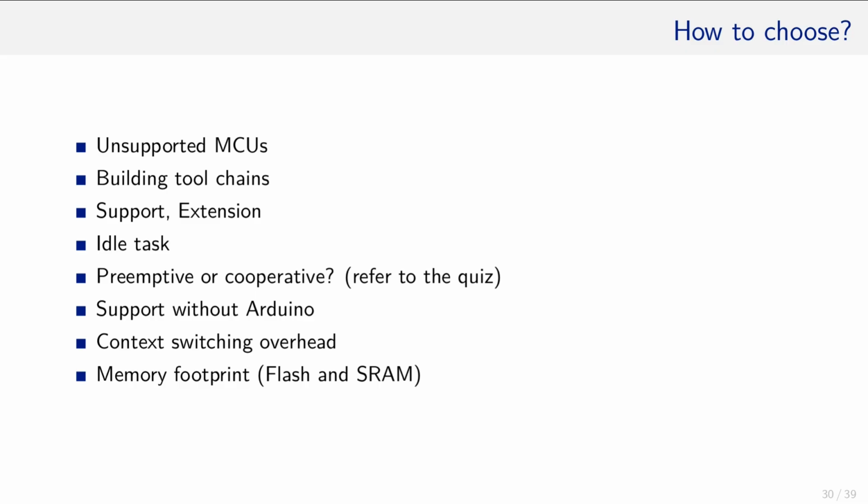Also, for reasons of reduction in power consumption, size, and overall costs, the user program is to be optimized for low power and high performance. Hence, the Arduino IDE is not used, but only AVR libraries. Therefore, function calls to, for instance, digitalWrite, digitalRead, pinMode, and delay are not available.